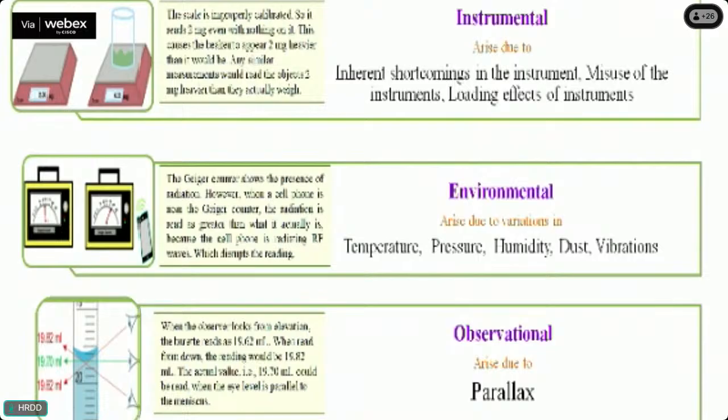It is always better to occasionally calibrate your measuring equipment, whatever it may be. There may be a standard operating procedure for your measuring device. Once in a while, whenever you find free time, try to calibrate the equipment and convince yourself that yes, the equipment is giving me proper readings. That way you can avoid doing a large set of repeat measurements. Each and every piece of equipment you have to occasionally calibrate and confirm its proper performance.